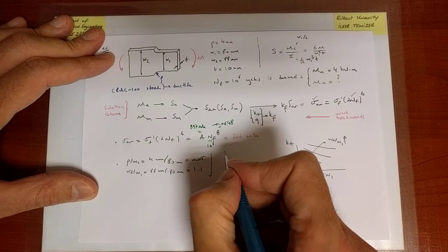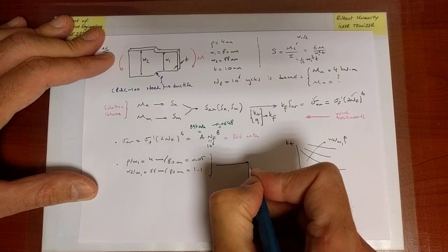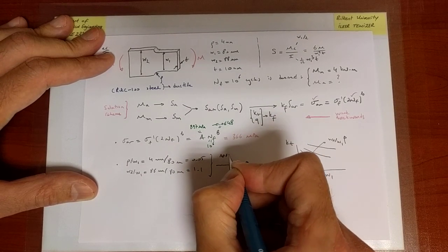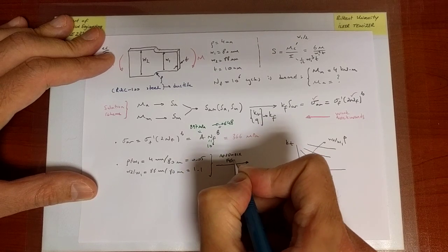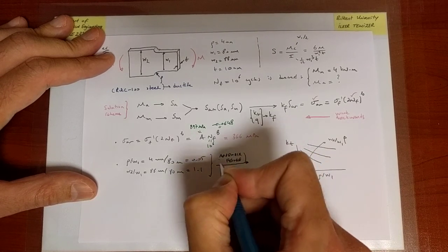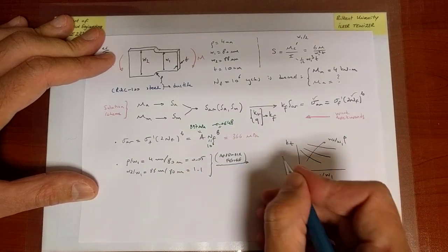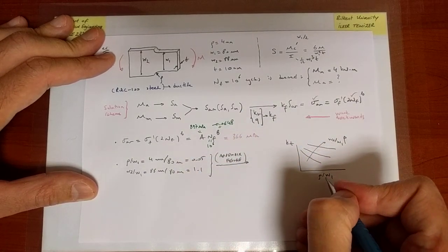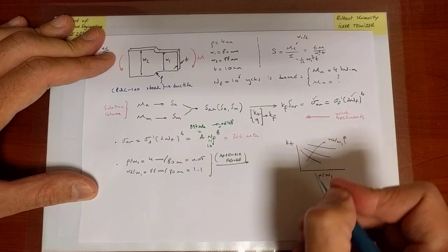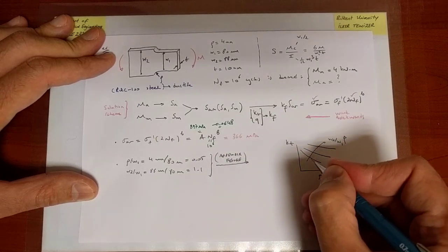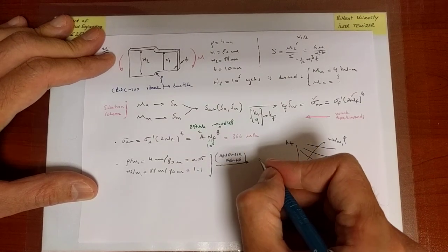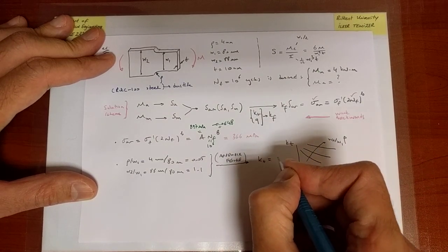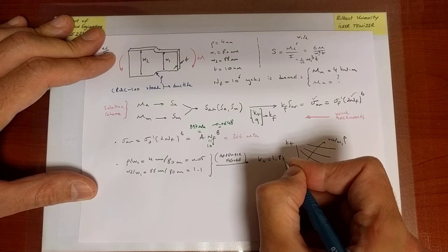So we can go to the appendix figure in the book, which looks pretty much like that, and read the corresponding value for this given rho over W1 and W2 over W1 ratio. If it doesn't fall on any one of the given lines, remember we have to visually interpolate, and KT can be found to be about 1.85.